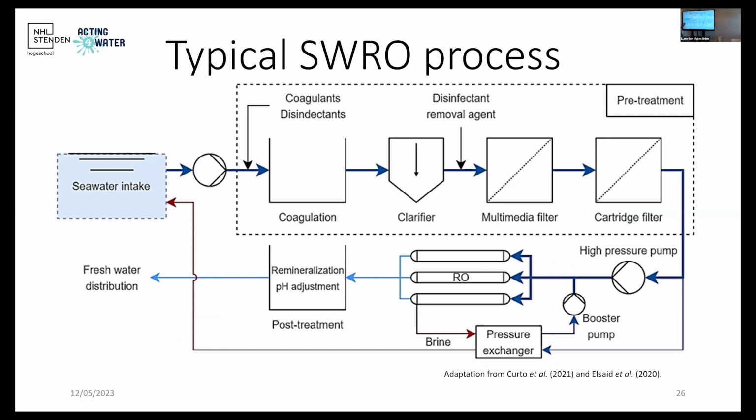As you could see, the advantages and disadvantages. You have to make some pre-treatment to avoid accumulation, biofouling, or any kind of scaling in membranes. There are many different ways. You can also do it with other types of membranes, for example, with filtration. But for the first plants, constructed between 10 and 15 years ago, the most used system was a coagulation followed by a multimedia or cartridge filter. So there is a necessity of pre-treatment, which is not that specialized in thermal systems.